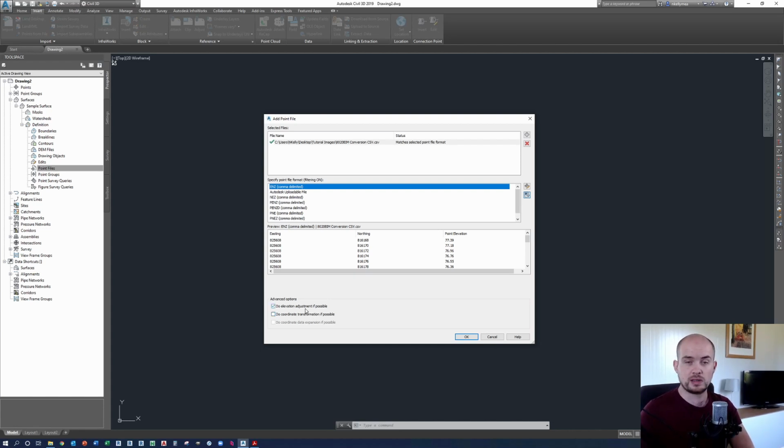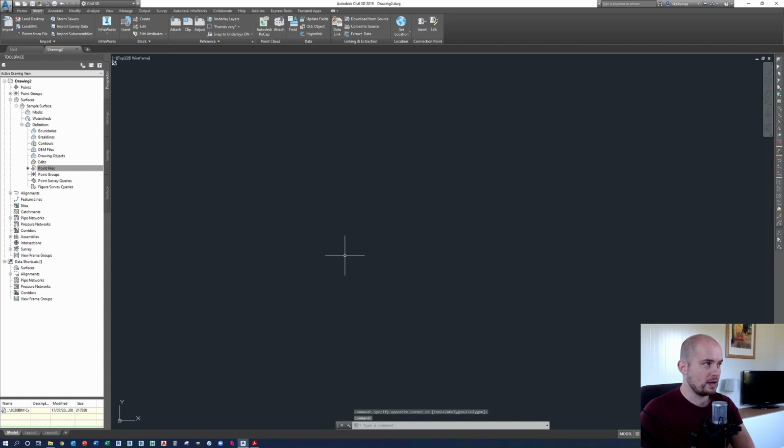But the elevation adjustments, it kind of tweaks to find the median between, let's say, egregious values that spike. So let's say you have something like a very, very dense object that is similar to the ground profile that is in the vertical plane, like a bollard or something like that. Using the elevation adjustment there, we can average out that so that we're only getting the surfaces. Okay, so pressing again, you have to understand that for the Lidar map in particular, we're not working to a degree of accuracy that you would from a 3D survey that's carried out on the ground. Okay, so I'm going to press OK, and we have brought in our data points there.